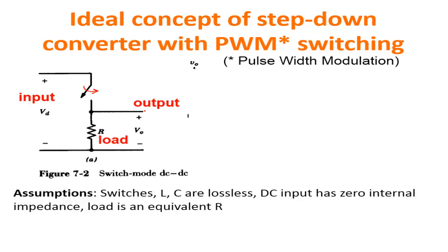And if you switch it on and off frequently, you provide an output voltage which is on average between 0 and VDD, depending on the duty cycle of the turning on and off operation. Therefore, by changing the duty cycle, you can change the average voltage that you provide on the output. This is the main concept of all types of switching regulators.